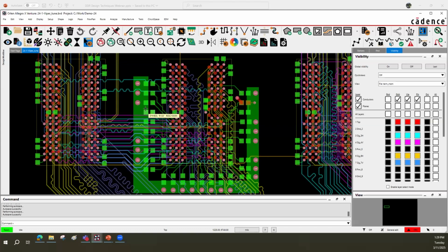I don't even place my termination resistors till at the very end, because what's important is from the driver to the receivers, of course, that flight time. And then at the end, I'm just terminating. I try to match those as close as possible, but they're not as critical, because what is it doing? Just terminating the signal. But again, the placement of those is important, and I'll just wrap that placement around the chip and then fan those out for my termination. So that's very important to keep in mind.